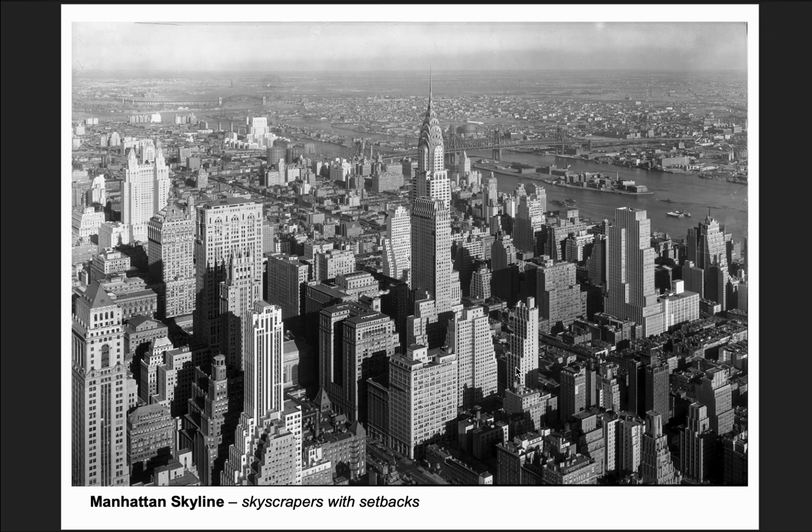And here's an early photo of the New York skyline, Manhattan. And you can see, I think this is the building over here. And you can see some of the buildings that were pre-1916 ordinance. This one is pre-1916, but some of them, you can see that they're all now tapering in their design. Okay, so either from the very bottom you don't occupy all your property, you have a setback, then you can go straight up, because you are not occupying your whole land. But if you are occupying your whole lot, when you go up, you need to taper your design.